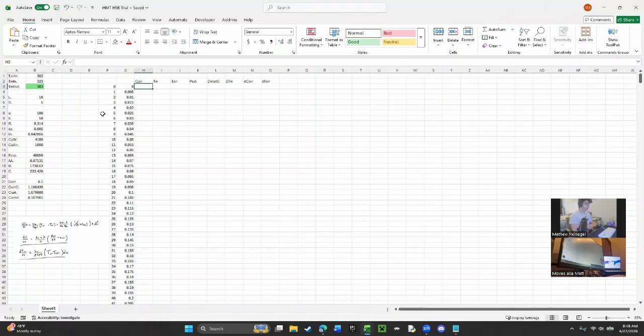All right, so from this point, we're going to be using the equations that we'd actually solve for. So this is the fun part. I'm going to do the concentration of the air coming in initially. This will be set equal to the temperature of the water coming in. This will be set to the temperature of the air coming in. Now for the saturated pressure, we're just going to use the same Antoine's equation that we've been using.